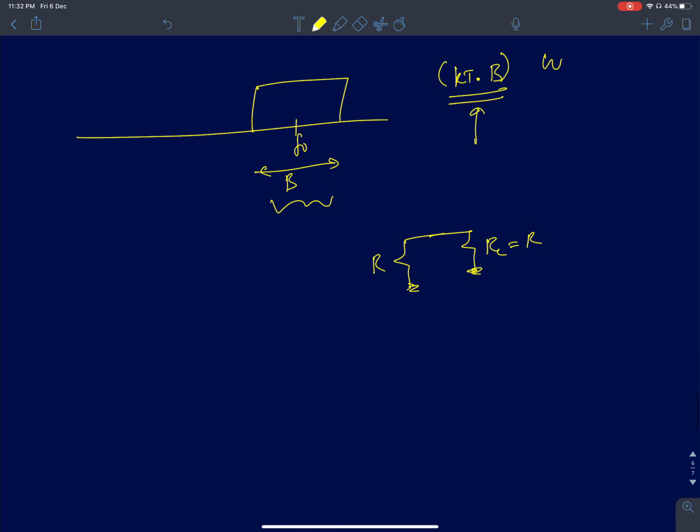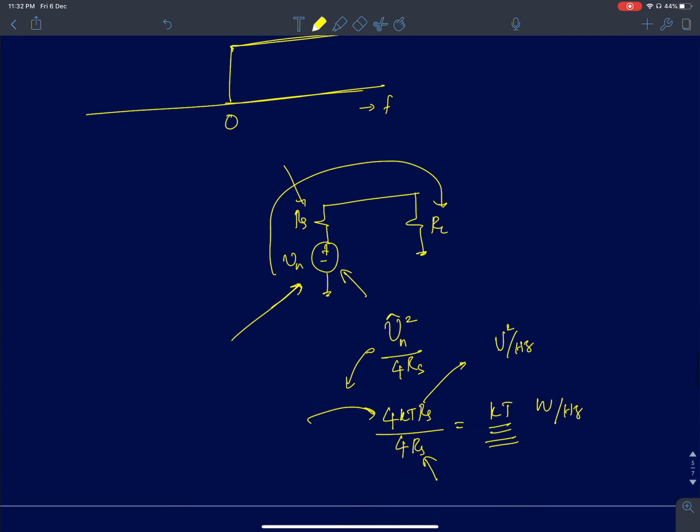Now this should sound counterintuitive, because it doesn't make any intuitive sense: from resistor noise, you can't derive useful power out of noise. It's a random thermal agitation of electrons. You can't extract any useful power. Then how did we derive this result? That comes from the mathematical model. We assume that noise is modeled as a voltage source in series with a resistance. So therefore, a voltage source, from basic electric circuit theory, can deliver power.